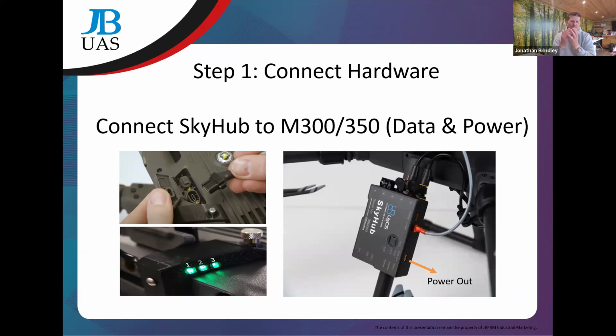So it will go through flashing 1 to flashing 2, and then when we get a flashing 3, it's telling us, look, I'm ready to go. So it's almost like some diagnostics of where it is at that moment in time during its boot up sequence, and it can also give us ideas on what's wrong with the system, if we've not got something connected up properly, or we've not updated the software or something like that.